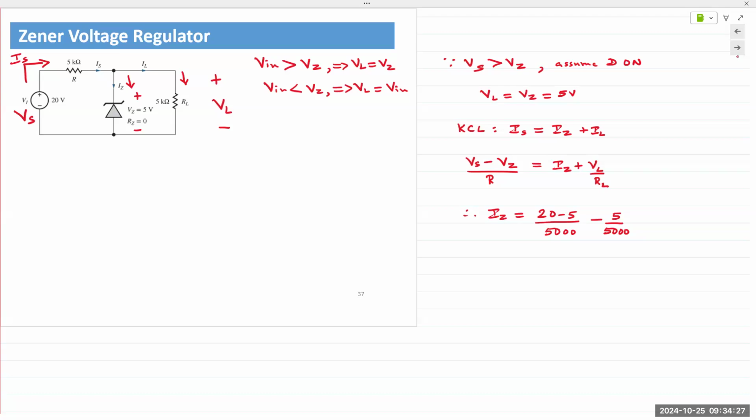It certainly is possible, yes. Now, the Arduino itself actually has voltage regulation built in. So it can take a 9-volt battery or a 9-volt source. And we connect it directly, plug it into the Arduino. The Arduino itself has a voltage regulator.